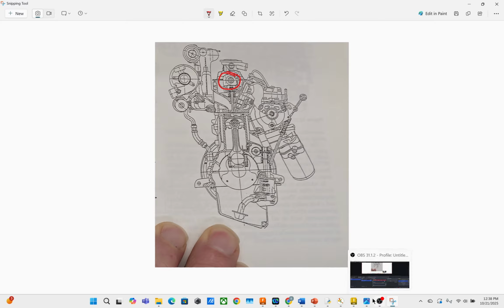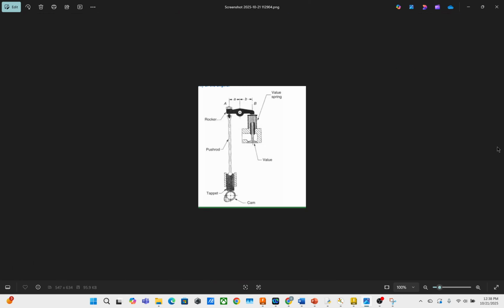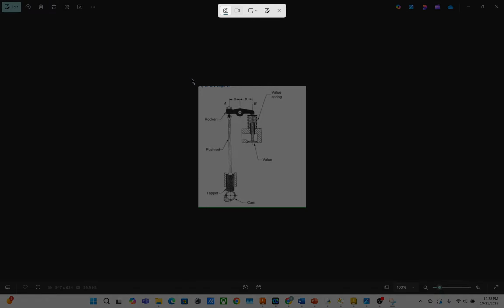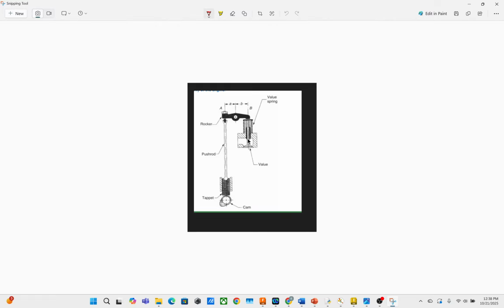Well, it looks a lot like a 12-valve Cummins if you're familiar with it. Basically, it looks like this. In a 12-valve Cummins, you have what's called cam in block, which means if the crankshaft was like here, you have your camshaft in the block right next to it. And what that means is that you unfortunately have to add all this stuff to transfer that cam motion over the cylinder and be able to actuate these valves, which is extra parts, extra cost, right?